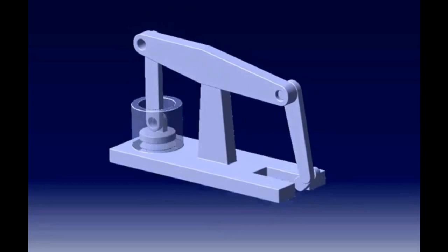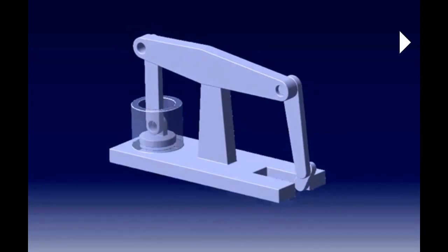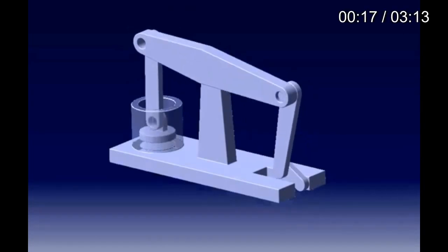The first one is called a beam engine mechanism. I think this is already mentioned. It was used earlier in steam engines and so on. As you can see, it is a modification of the four-bar mechanism. You have a crank connected to another bar, an oscillating bar, which is fixed with a stand. On the other side, instead of a rocker, we constrain the link to a straight line motion, that is, a sliding motion. This may be given to you: the beam engine mechanism.